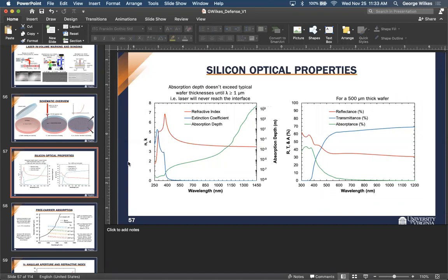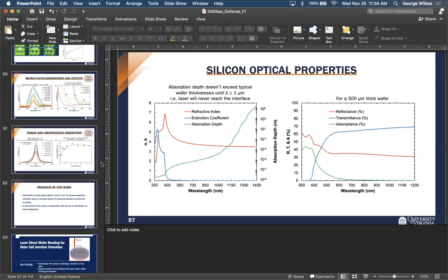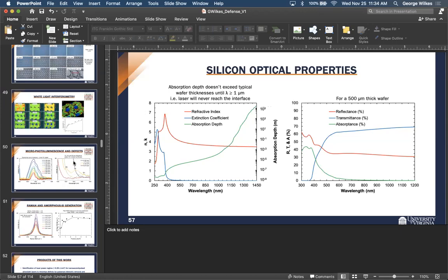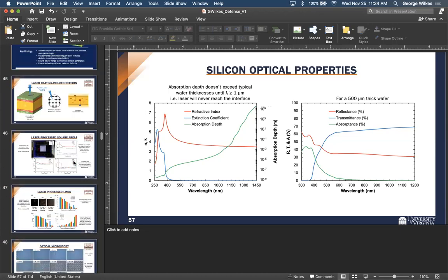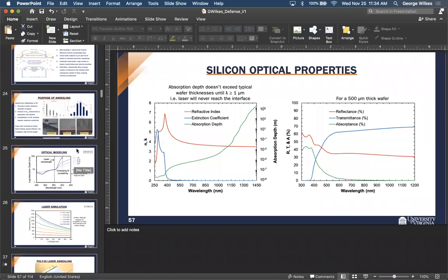But you're annealing the polycrystalline silicon, not the amorphous silicon, which means it's the grains of the crystalline silicon in different sizes. So I was curious if it is a morphological effect or an intrinsic effect. Because crystalline silicon has a stable n and k, you wouldn't expect it to change significantly that way, even though you could see the color change. So I was wondering if you took a look at AFM-type surface morphology observation before and after the laser annealing.